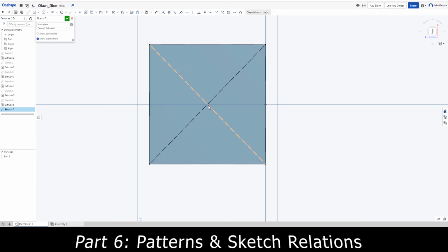So now what we're going to do is we're going to work on our circles. So we're going to select our circles, and then we're going to find any point on this line. As long as this line is turned orange as opposed to black, we're going to select it and just put our circle there. That means that it's in a straight line. And then for the center one, we're going to want to make sure that we're exactly in the center. So as you can see, there's an orange box that appears right there by where the cursor is. So once you're on the orange box, click and hold and make your circle. And then the third one can be anywhere as long as it's on that line. Perfect. And don't worry about the size of them because we're going to make them the same very soon.